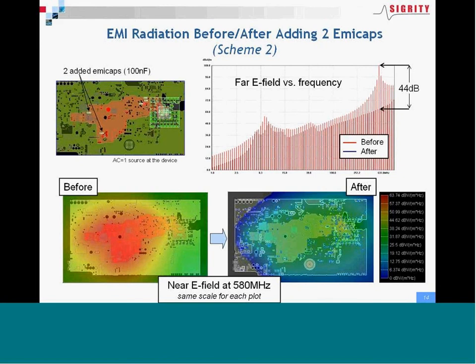Okay, and another person is asking, I guess as a follow up on the question about where the frequency peak got pushed out to, there's an observation about issues at high frequency, above a gigahertz, for emissions. So can you speak to that? Yes, the peak will push out to a higher frequency, and maybe a lower amplitude. And if you know exactly at what frequency is more important and what frequency you have a lot of current excitation, those are the frequencies you have to watch out for and try to move the peak away from.